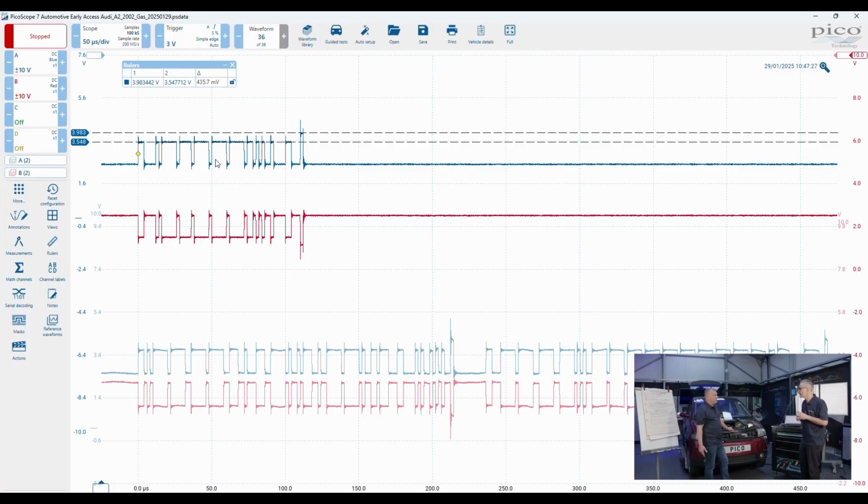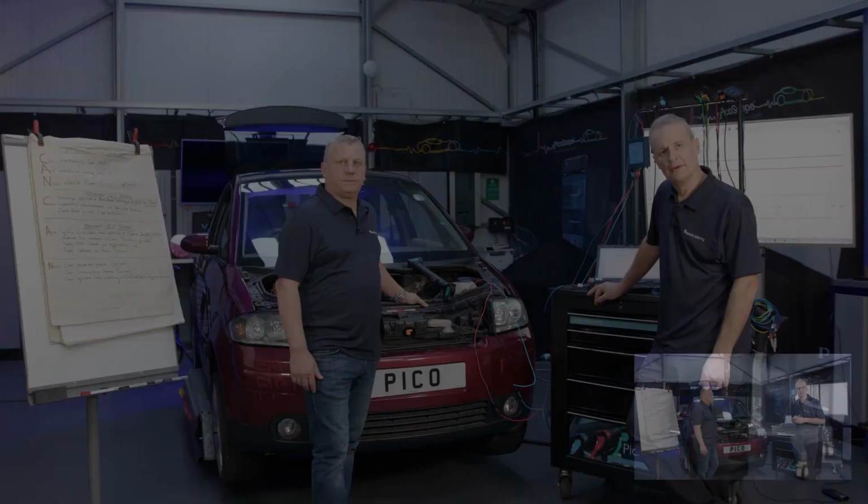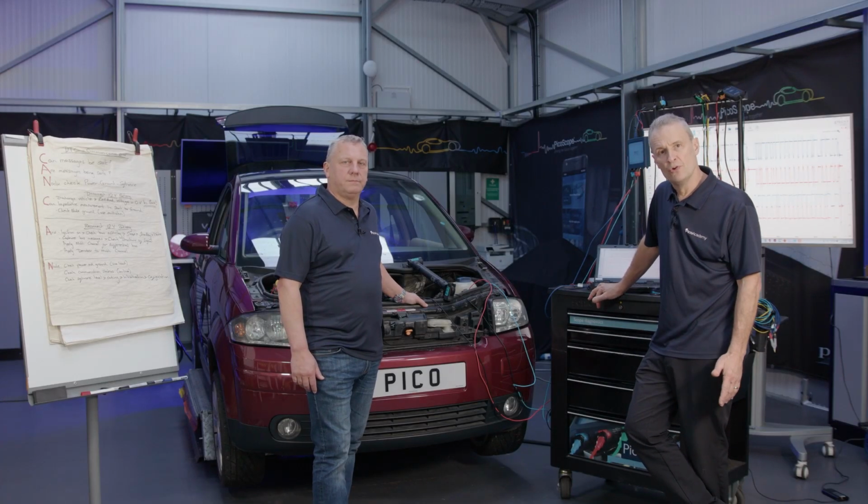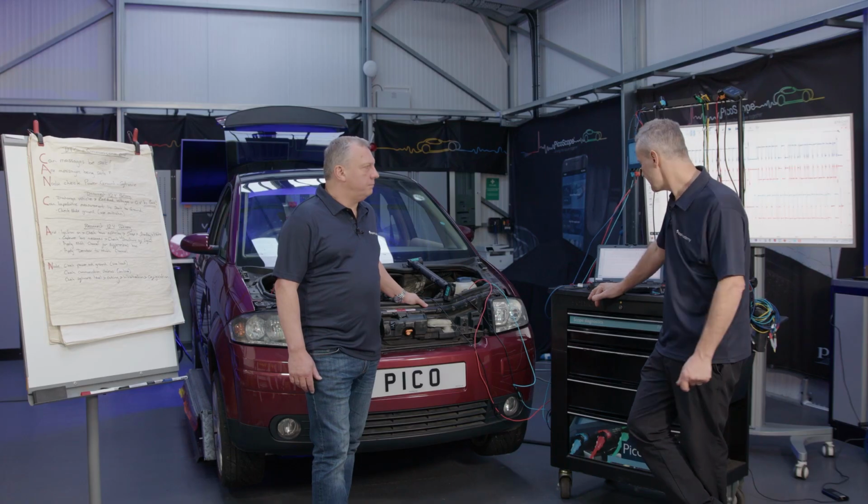So, that's purely because they're on a parallel circuit? Yes. And they've all broadcast at the same time? Now, I think on this vehicle, 6 ECUs. It'll be something in the order of that, yeah. It's relatively small, but nevertheless, there's the effect of 6 ECUs all acknowledging receipt of this message. Okay, so we're happy that the signals are correct, we've got the right baud rate, messages are being sent.